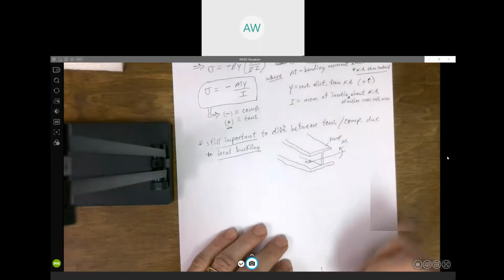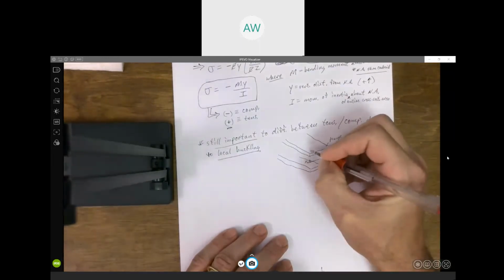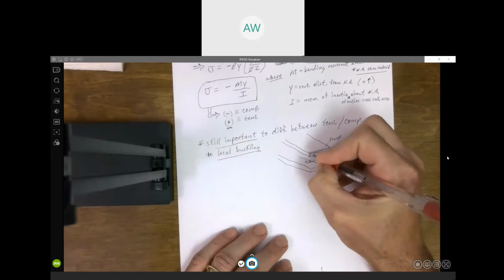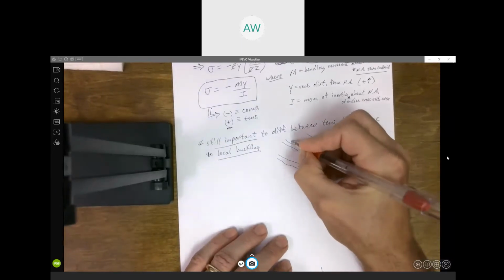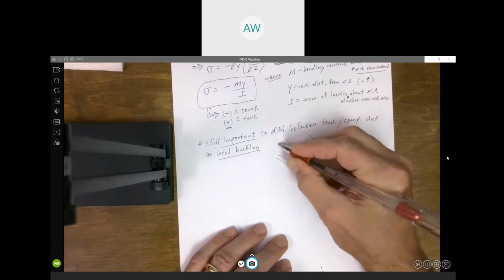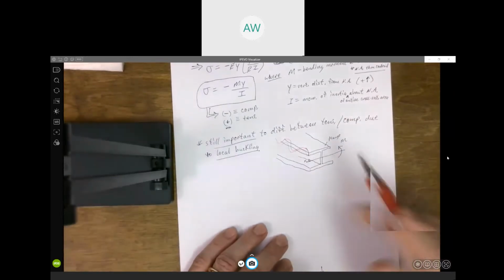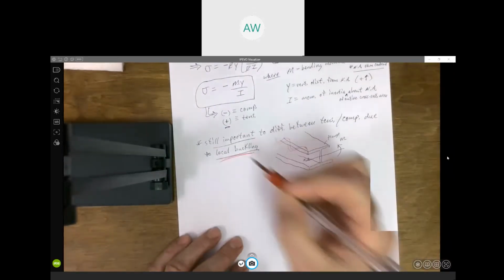And again, it's not going to bow out like that. What you would see is basically looks like waves. What you would see is this, the flanges here on that I-beam are going to ripple. That's what we call local buckling.